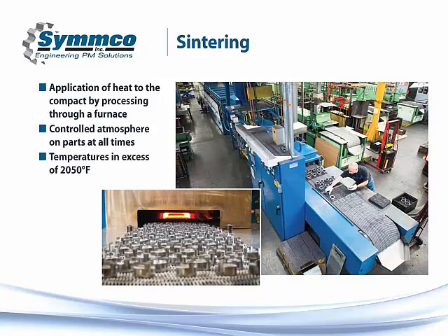It is in a furnace for typically about 2.5 hours, and that would account for a gentle cycle going up, maintaining that 2,050 degrees Fahrenheit for a significant time, and then running through a series of coolers that allow the part to come out at a temperature that is not dangerous to the employees in the area. Generally handleable by hand when they come out if you had to.